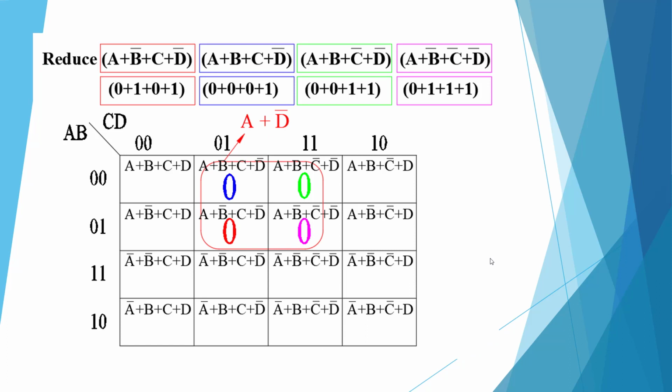Here I am showing a KMap, and this is POS, product of the sums. So what we're going to do is plot these and then simplify it, since these four are all close. We're going to convert those, and we're going to drop out the b, and we're going to drop out the c, and we're going to be left with a plus d bar. That's what this simplifies to, and I'm going to program this into Verilog.